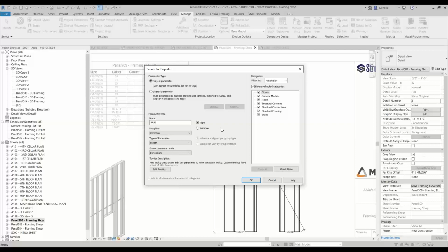The thing that could be variable would be maybe the type of wood or the treatment of the wood. Well, I'm more familiar with steel, so I'll give you a steel example. Maybe you need galvanized steel in certain areas, or you might want to use a different material for another area of the project, right? Or you just want to apply different finishes to the object. So what you could do is set that up as an instance, because the 2x6 doesn't change.